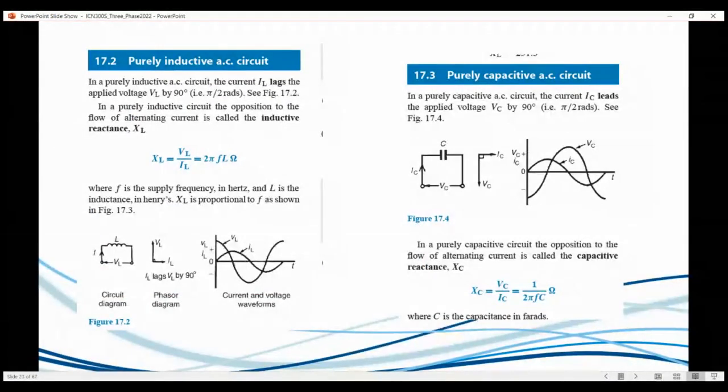What is important is inductor. This formula over here, your inductor produces an inductive reactance, and the equation for it is X subscript L, where X_L is 2πfL. We're going to be using it a lot, so get comfortable. Obviously, you've touched on it a bit with AC, I think. And then your capacitive reactance is 1 over 2πfC.